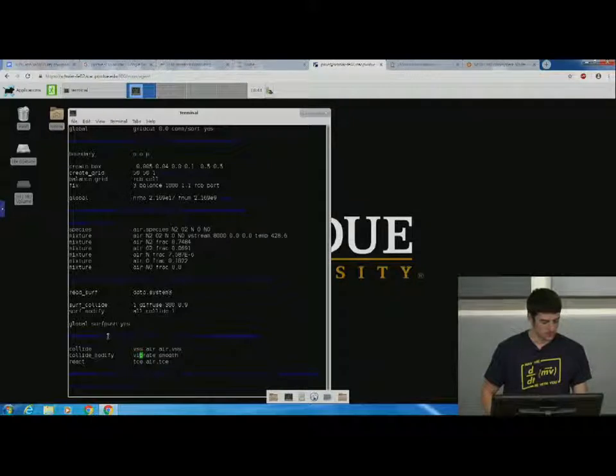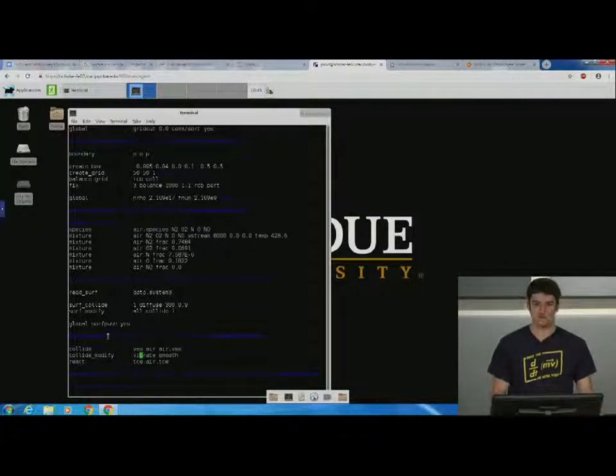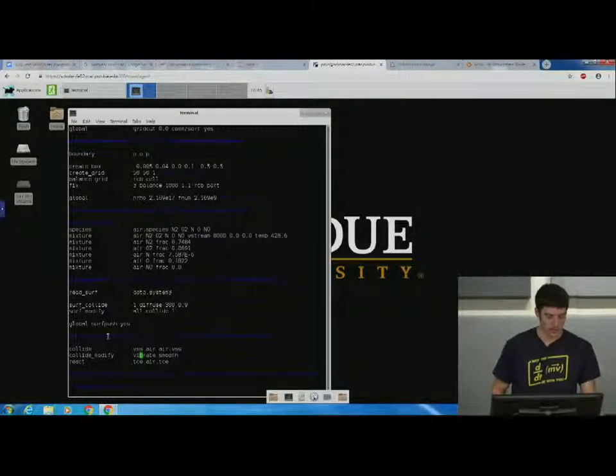By saying collide, modify, vibrate, smooth, this is activating the vibrational mode of energy. Naturally, it's not activated. That's one thing SPARTA added more recently, a vibrational mode. So you have to specify it in here, which for lower enthalpy flows isn't really important, probably not even worth doing. But in this case, being a re-entry problem, vibrational energy is huge. So that's why we have to do that.